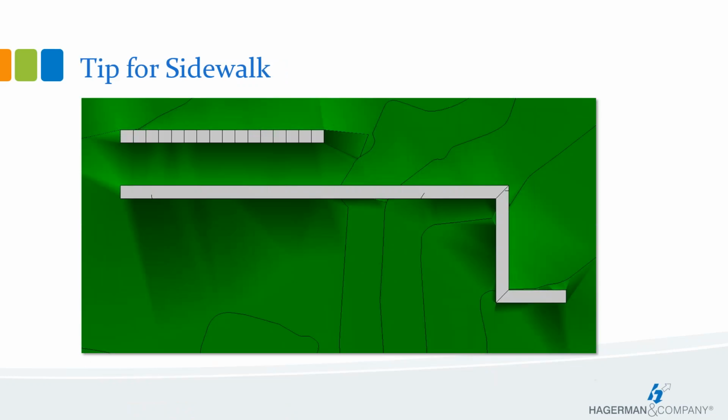Okay, so here's a helpful tip just for sidewalks. Which one looks better, top or bottom? Well, the top, right, with the control joints. How did I do that? In the bottom one, my sidewalk was drawn with a continuous model line. The top one was drawn with the model line split into 4-foot segments. Very good trick to make it look like a real sidewalk. Pretty easy to do.